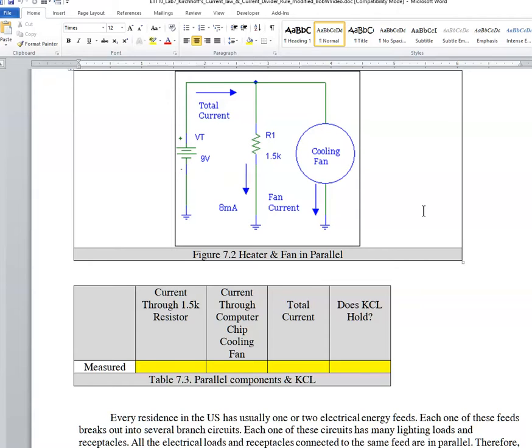As the fan blade sped up, the current would go down. You could, again, simulate a slower fan by putting your finger against the hub of the blades, not in the blades, and that would show that the current would go up again. Therefore, that fan motor is not quite as linear as a resistor, because a lot happens depending upon the load on the electric motor.